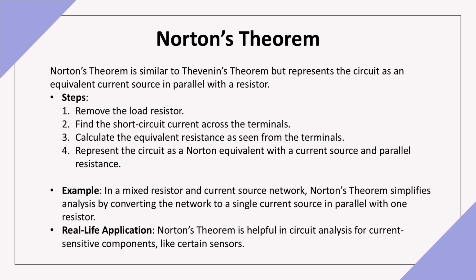discharged. The relationship between Norton and Thevenin equivalence is: Norton current equals Thevenin voltage divided by Thevenin resistance. Norton resistance equals Thevenin resistance. This is particularly useful when working with current-sensitive devices, parallel connected loads, current amplifiers, and sensor circuits.